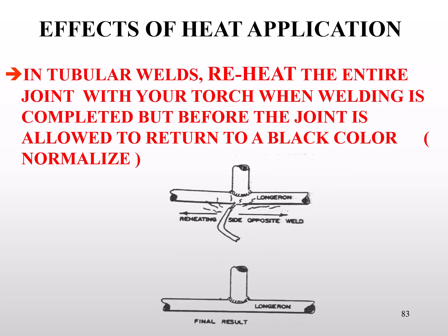In this case, to save the part, we can reheat the entire joint nice and even, not to melting point, but elevate its temperature. And then we're going to allow it to slowly cool back down. That'll release the stresses in the material. It'll also help us bring our material dimensions back to a more desirable straightness, or whatever the characteristic we're looking for. When we reheat and allow them to cool slowly, that term is known as normalizing.